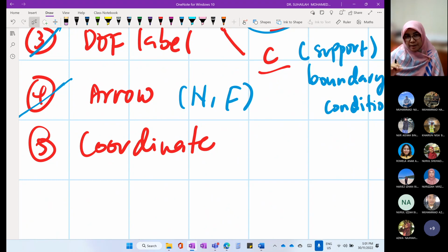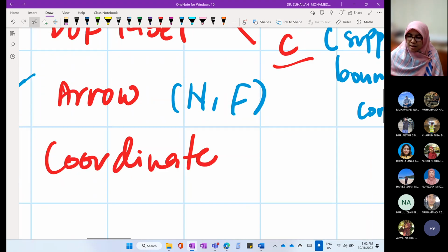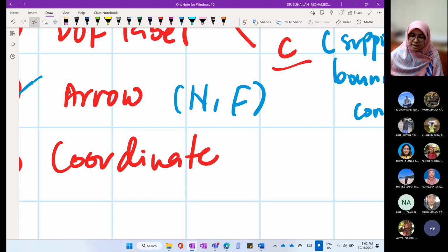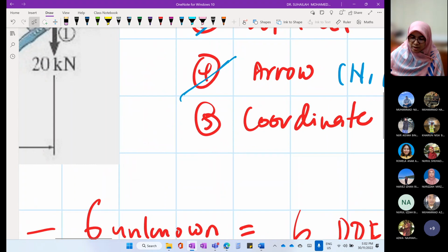Cx and Cy, or lambda, are actually the unknowns that you have to determine in order to calculate K. Cx and Cy are in the appendix. If we identify the near and far end based on the arrow that we put, it is much easier to identify Cx and Cy.